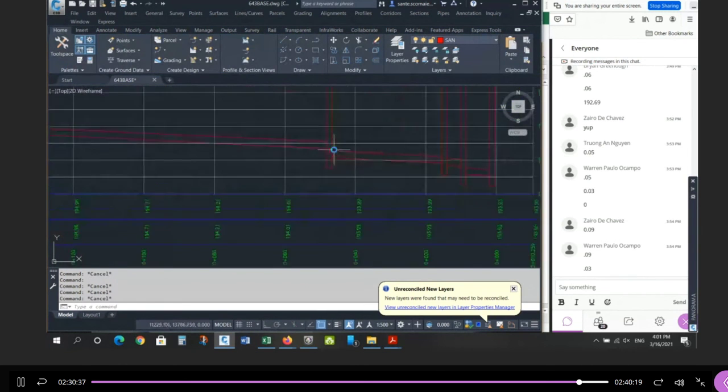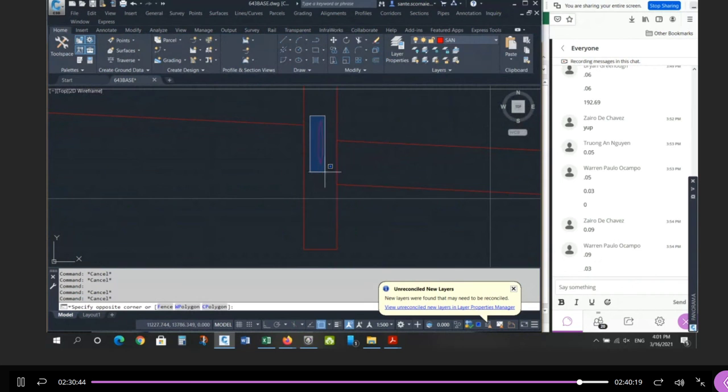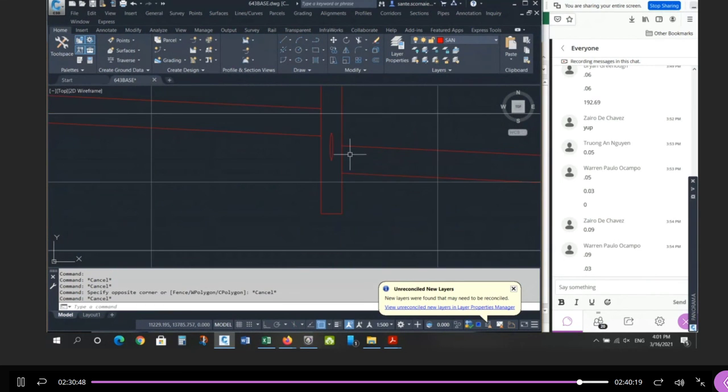So right here is that intersection. Look here. I drew this pipe and I drew this pipe, but I didn't draw the pipe on street B, but there it is. It looks like it's connected at 90 degrees. So that ellipse that you see is because there's a third pipe not drafted in the profile.